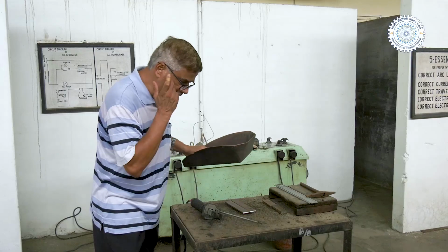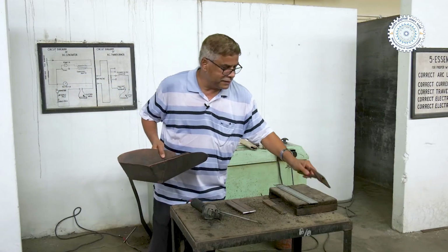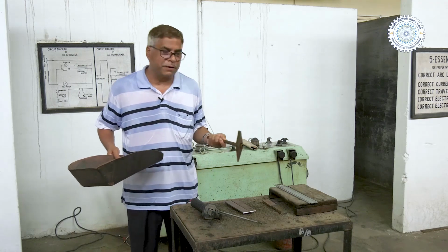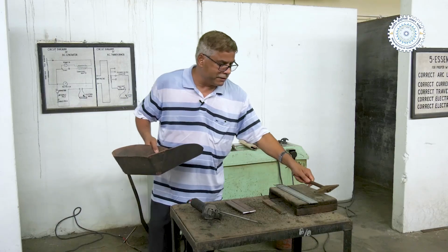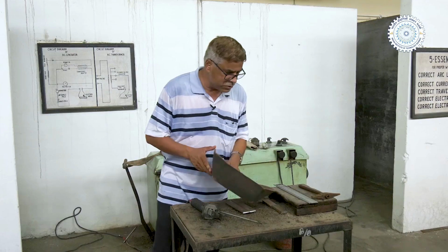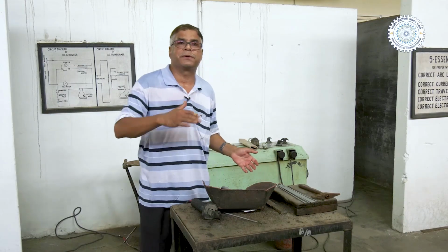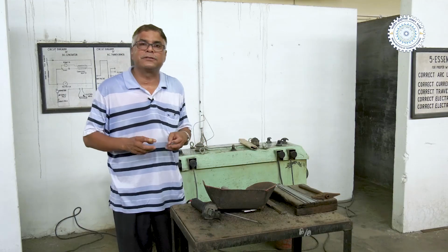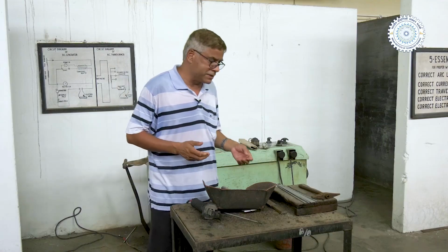Apart from these two things, there is also the hammer. This is called a chipping hammer, which is used to remove the slag which has developed after the welding over the plates. You can see a number of electrodes are there because these are consumed in the process. So, indirectly this is also a consumable type of arc welding, where the electrode itself is consumed.